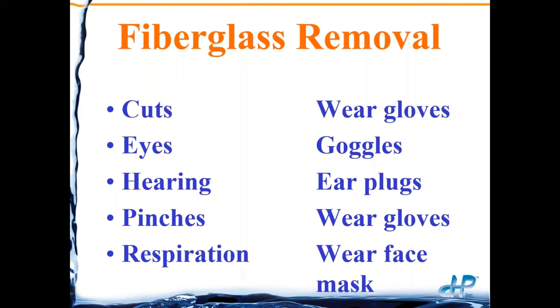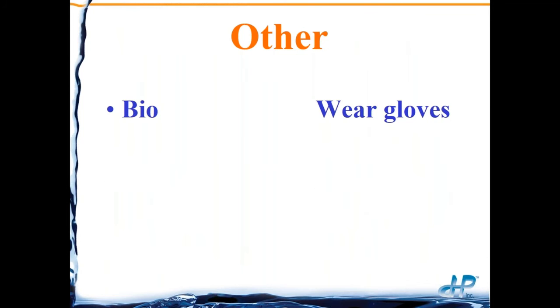in the air, so we would recommend wearing a dust mask or face mask so you don't breathe in that fiberglass. The other issue you can have with element autopsy is, since almost every element we have has some bacterial growth in there, we don't want to be handling that and possibly getting sick from the bacterial or biological growth.